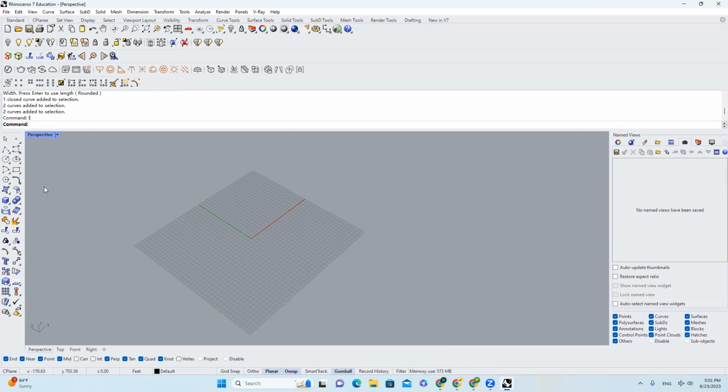Again, the next thing, which is also very important inside of Rhino, is those toolbars here. We can start from the points. You can click and space, click, space, click. Again, space will just allow you to recall your last command. Or this little triangle here, click this. You can click multiple points without using space again. And then this polygon tool, right? You can just draw a polygon.